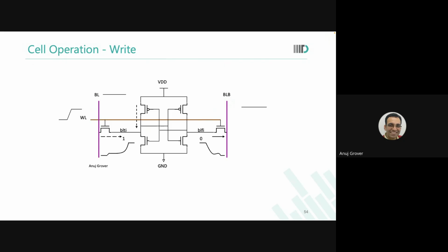And do you also notice that this no longer is a digital 0-1 operation that you thought it would be? In memory we only store 0 or 1, but you see what interesting waveforms there are. Go home and simulate any 6T configuration, just simulate. Open the waveform, see how they are. Keep any size for now. Let's see what is happening.